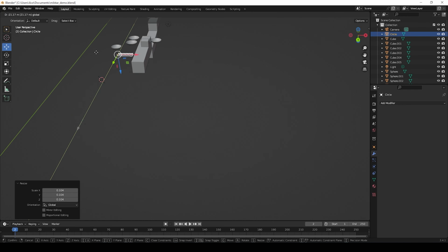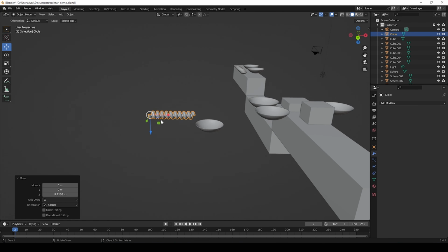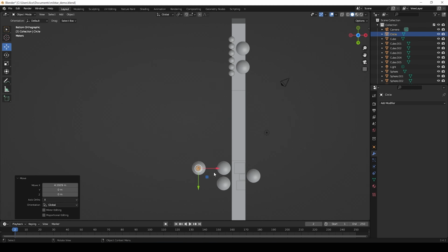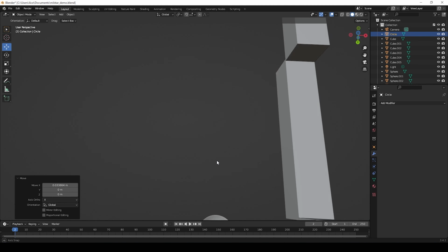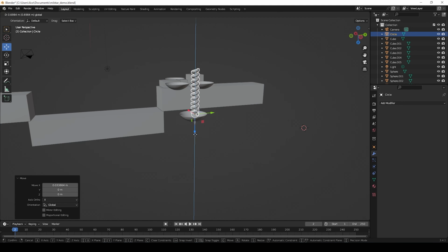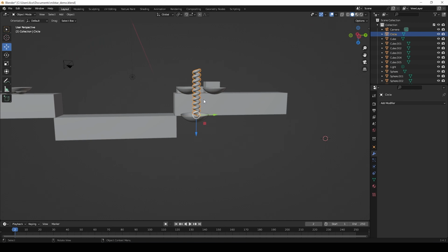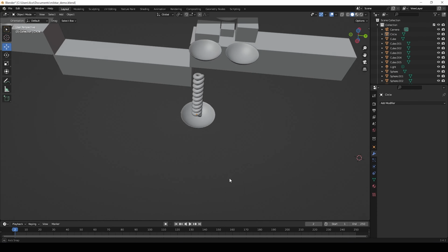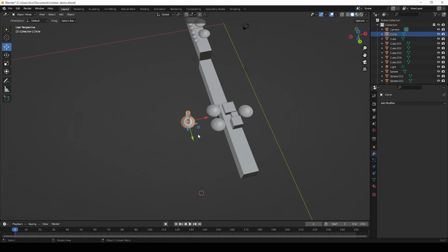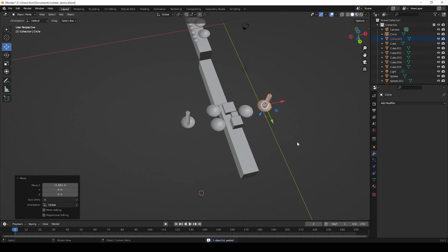Something like that. We'll move that over to the dish that it's going to land on, which is going to be that one. And we're going to go ahead and rotate this around the y-axis 90 degrees. Go into the -Z and try to line that up with the center of our parabola. And we'll just bring that kind of down there. And I think that's looking pretty okay. Maybe bring it back just slightly. Great. Now we'll just copy that and we'll paste it and we'll move one over to the other side.